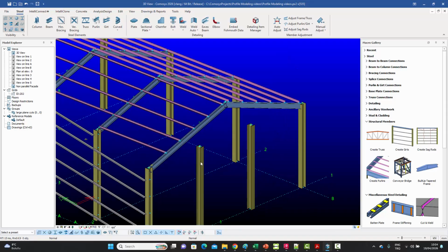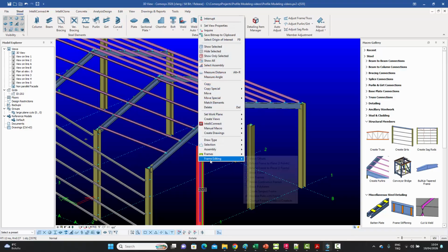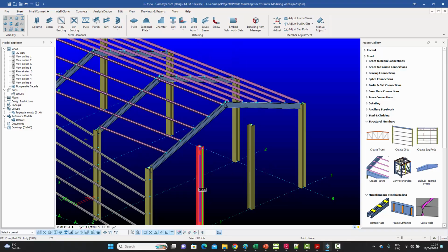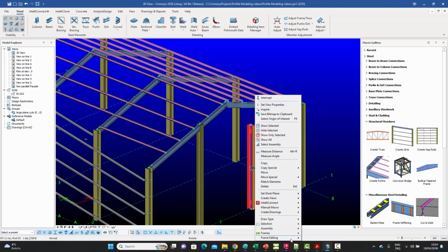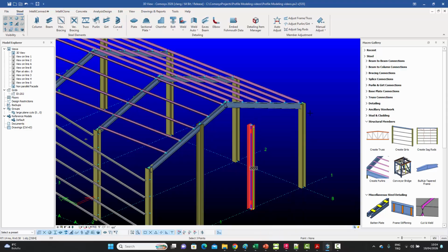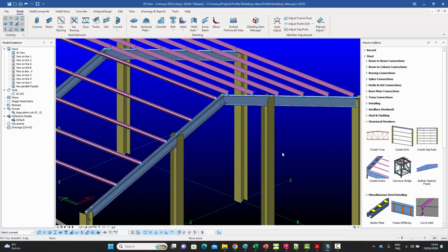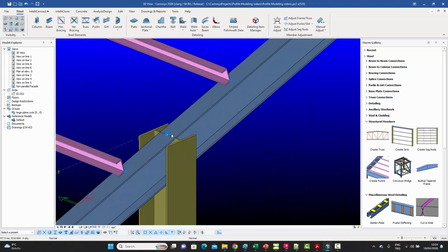And now what you can do is you can select this one, right click, and say with 3 points, and basically show any 3 points on that roof, and it's going to be extended. And select this one, right click, show any 3 points on that roof, and that one is going to be extended as well. If you're slightly unsure, first of all, if you got the nodes on, you'll see the blue node, which means you've connected.